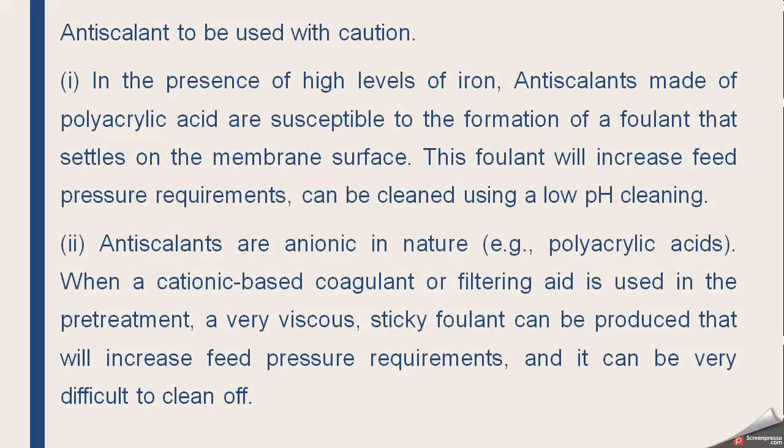Now, in the presence of a high level of iron, antiscalants made up of polyacrylic acid are susceptible. These are practical considerations, leading to the formation of a foulant that settles on the membrane surface. This foulant will increase the feed pressure requirement and can be cleaned using a low pH cleaning. So if we have high iron and the antiscalant is based on polyacrylic acid, then the foulant which settles on the surface can be cleaned using low pH.